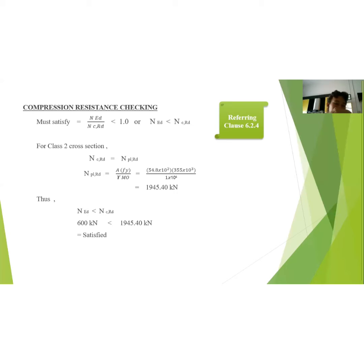The compression resistance checking. Referring to clause 6.2.4, we must satisfy NED divided by NCRD is smaller than 1.0, or NED smaller than NCRD. For the class 2 cross-section, we must find NCRD, but it is the same as the formula of NPLRD, where A times Fy divided by gamma M0, we get 1945.40 kilonewton.